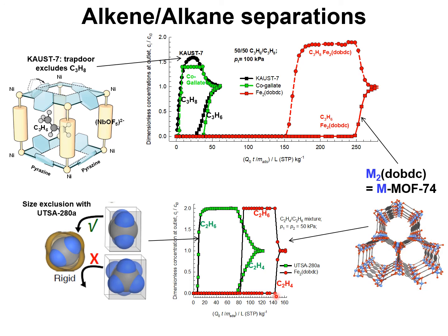A significant proportion of ethane is also adsorbed along with ethene, and the significant adsorption of ethane has the effect of causing a lower purity ethene product in the vacuum blowdown phase.